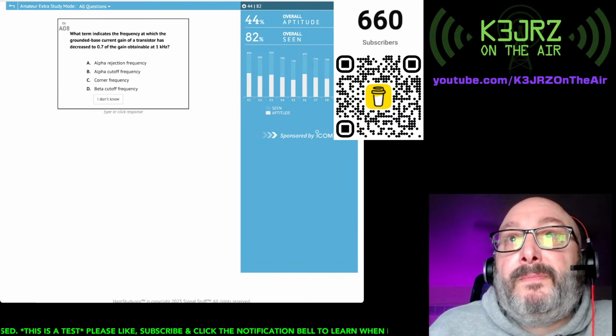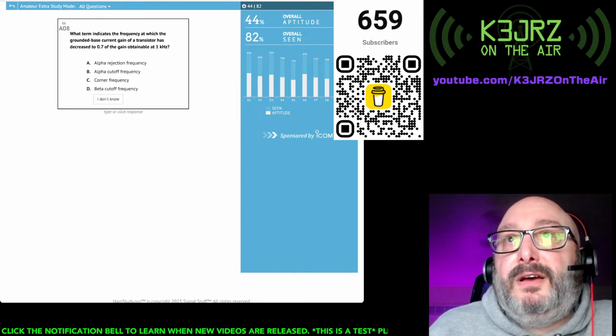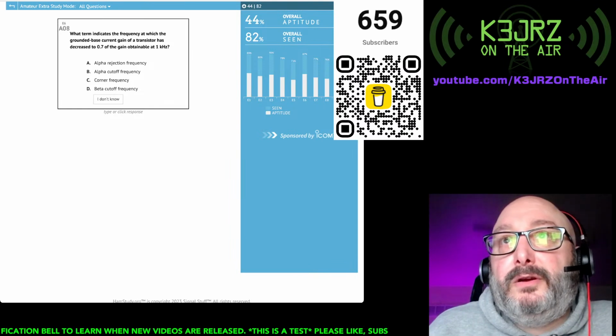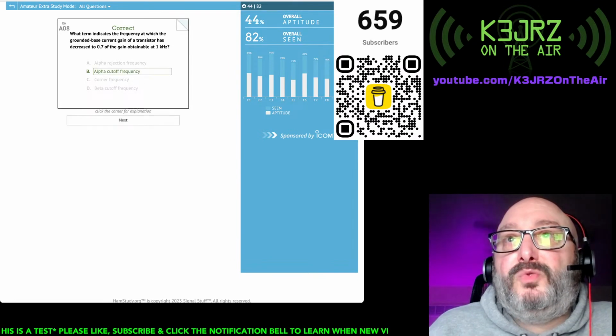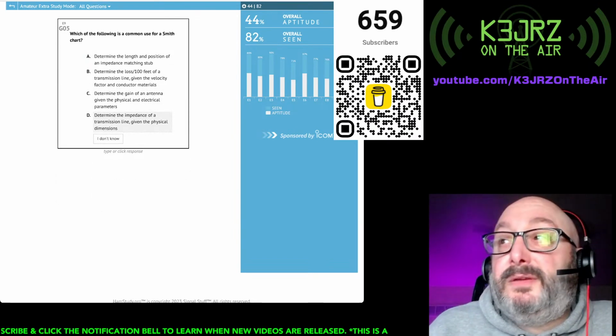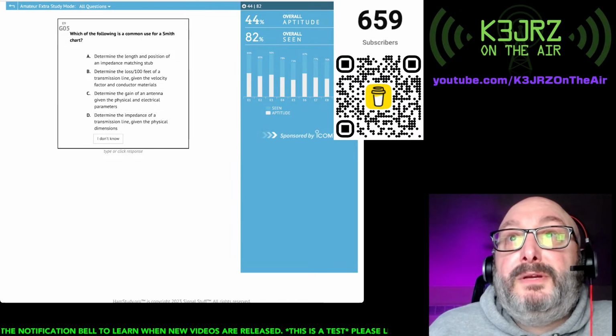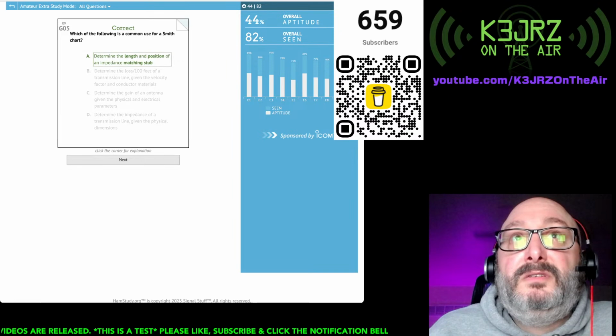Exactly. You never will. What term indicates the frequency at which the common-base current gain of a transistor has decreased to 0.7 of the gain obtainable at 1 kilohertz? Ooh. Alpha rejection. Alpha cutoff. It is the alpha cutoff. I've seen this once before. I remember that. Now I know your pupils are watching. This might be a short one. Which of the following is a common use for a Smith chart? Determining the length and position of an impedance matching stub. I remember that one. I was getting smart.